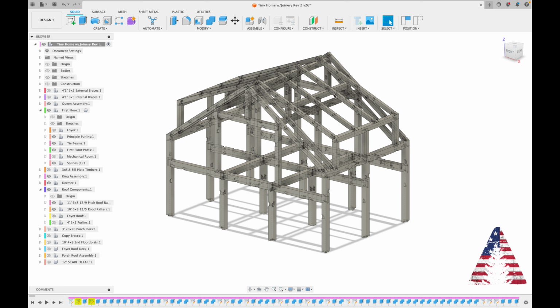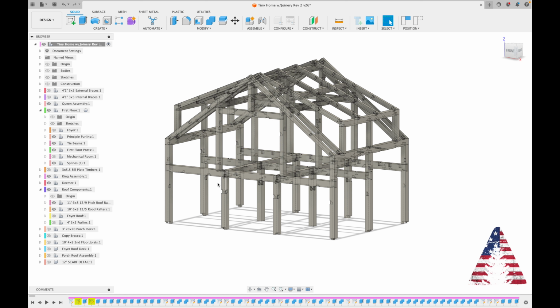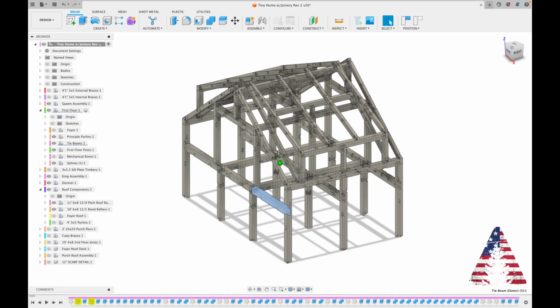all that to say that for me, this design choice was more aesthetic than anything. Well, aesthetic plus the orientation of the house and understanding the limitations of my material. Using maple, I would never be able to find a 30-foot long maple large enough and straight enough to make a 30-foot tie beam. The limitations of my material prevented me from doing an integral bent design for this frame. So those are the two factors that led into my choice here.